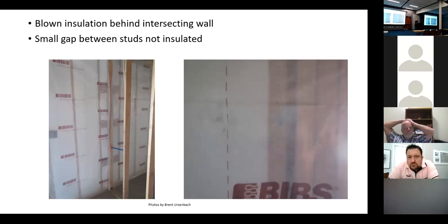So here's the OSB on the exterior wall. Here's outside, here's inside. What's the temperature of the inside surface of the OSB when it's 10 degrees outside? It's not 10, but it's close to 10 degrees, right? The insulation's here, just bad insulation in the cavity. So this inside surface is going to be cold, right?